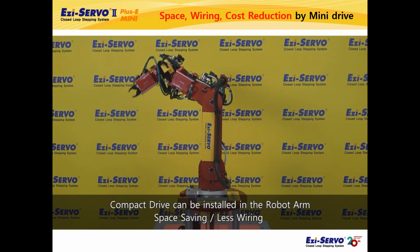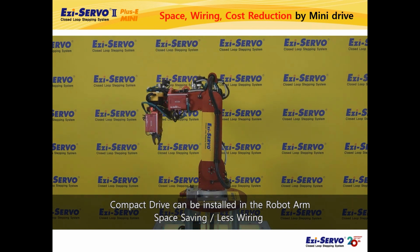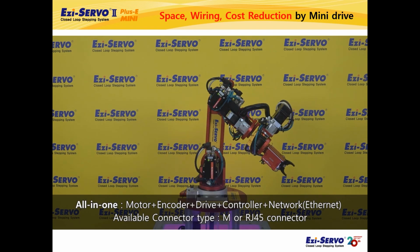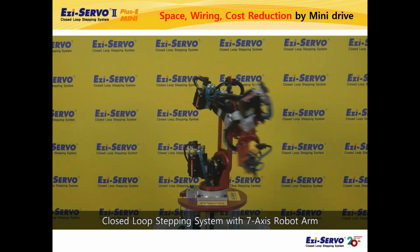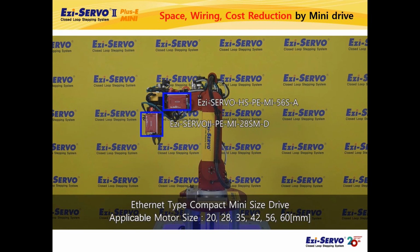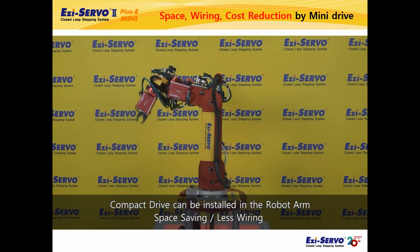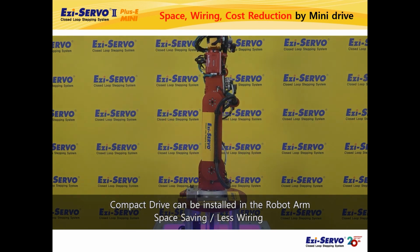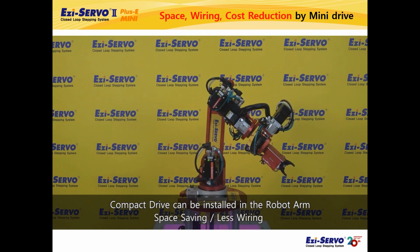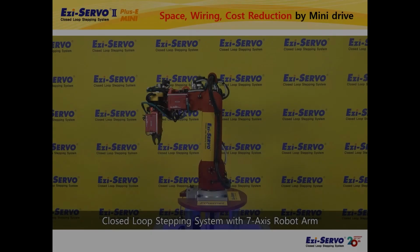In addition, there is no need to wire a motor and encoder because an Ezi-SERVO 2 Plus-E All, an all-in-one product that combines a motor, high-resolution encoder, drive, motion controller and Ethernet network, is applied to 5 out of 7 axes. Therefore, when using the mini drive Ezi-SERVO 2 Plus-E Mini and the all-in-one drive motor, there is no need for a separate control box. The actual wiring is only one Ethernet communication line from the PC and a 24-volt power line.